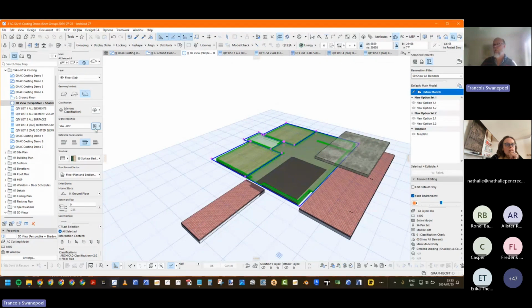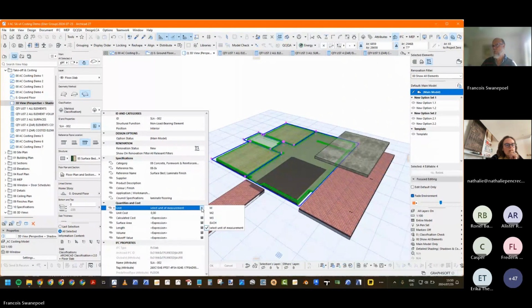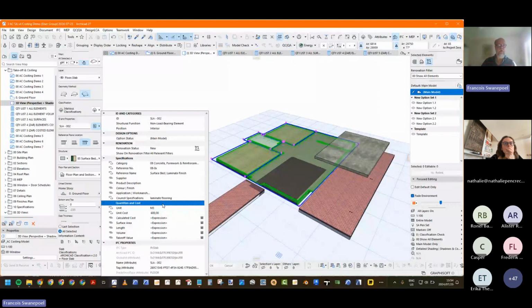And go and check there's the solid floors, that classification is correct. And I want to assign a unit. So let's go, I think it's cubic meters for this one. While I'm on the screen, these little tables look like Excel spreadsheet icons. If you click this, it will populate the calculated value for that selected item in the preview of the properties on the element settings itself.